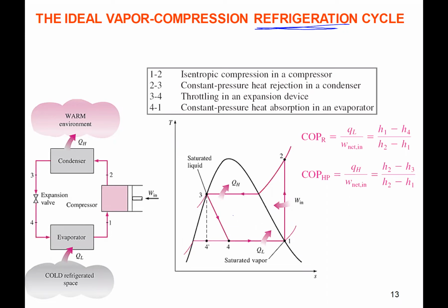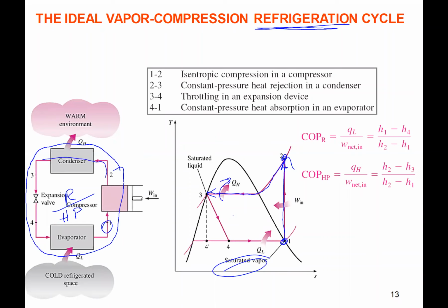All right, so in our refrigeration cycle, that was our circle back in chapter 6, where we did R or HP for a heat pump. This is now what's inside that circle. If we work our way around the diagram, starting at 1, we're a saturated vapor going into a compressor, and we compress it up to 2 isentropically. We have our heat rejection process, so we go from 2 to 3, condensing that fluid.